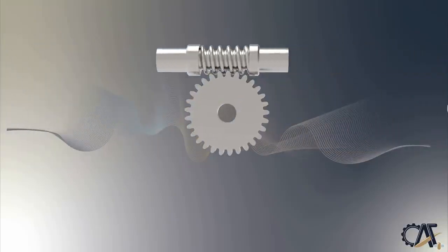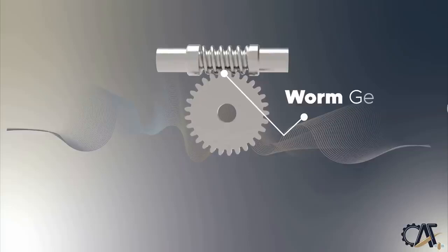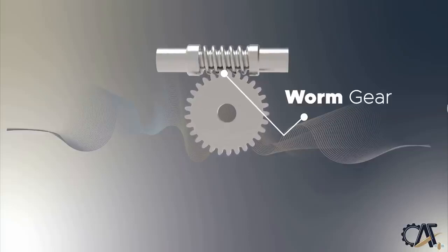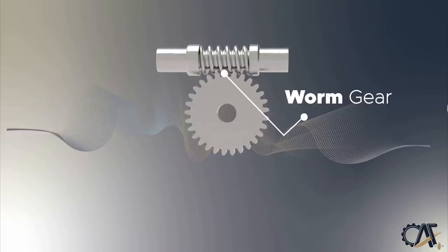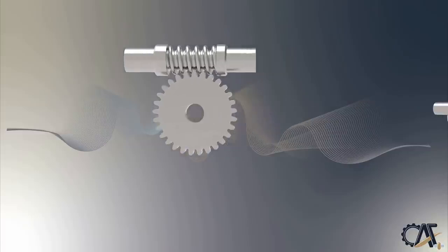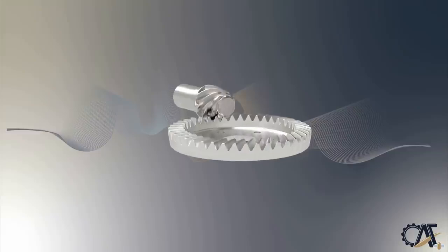Worm gears are used to transmit power at 90 degrees on non-intersecting shafts. Worm gears produce thrust load and are good for high shock load applications. A screw-shaped cut on a shaft is the worm. The mating gear is the worm wheel. The main disadvantage of worm gears is their low efficiency, which can be close to 15% due to the high friction and associated axial stresses.